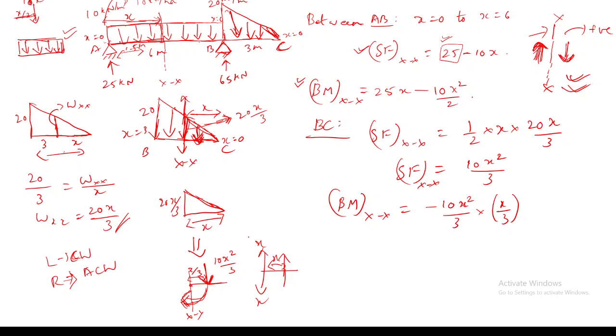Sir, from the right, if it is anti-clockwise, then it is positive. Yes, right, anti-clockwise means it is positive for bending moment. Usually, if we consider the entire beam and you have some concentrated moments like this, then only you consider that sign convention. Since here we have uniformly distributed load, point loads, everything, you have to go by this procedure: left clockwise, right anti-clockwise.